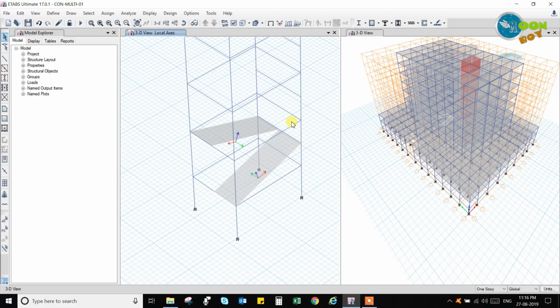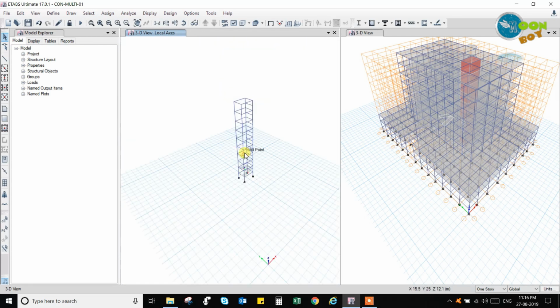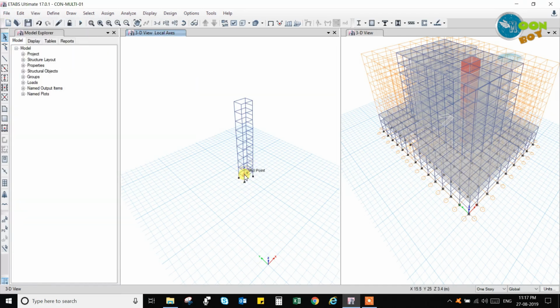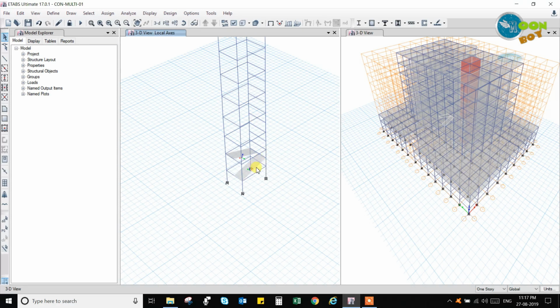Thank you. In this video I'm going to show how to load the building and do analysis using this structure. In this structure I will change the diaphragm D that is none to D1 diaphragm, and I will make it a semi-rigid diaphragm so that I can show you what warnings come up. And similarly, for verification, I will show you how to clarify the warnings and how to get rid of them and do the analysis without thinking about the warnings.